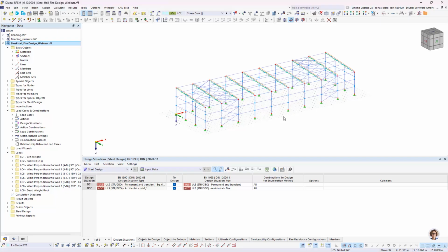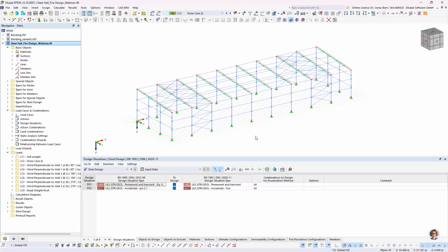to the model. And this temperature we could either derive by the standard temperature curve, or we could derive it by some other specification or a parametric fire curve, CFD analysis, whatever it is coming from. We need to make some assumption about to what degree our structure heats up. And then we can apply this temperature load via, for example, a member load.